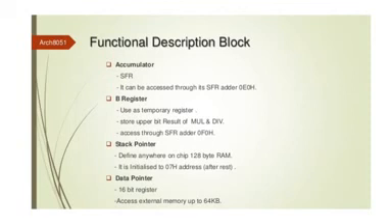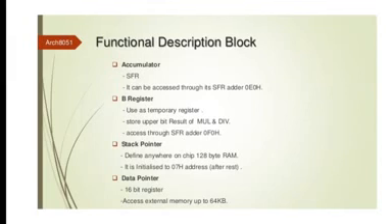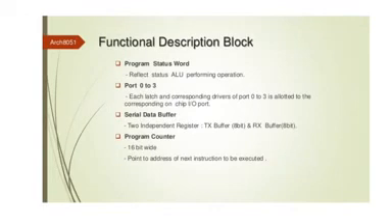These are the two instructions for data and code. Data means RAM, code means ROM. Whenever you use data, you write MOVX, and whenever you use code, we write MOVC. C means code here, and X refers to external. That's it. Now after the data pointer, you have the program status word.